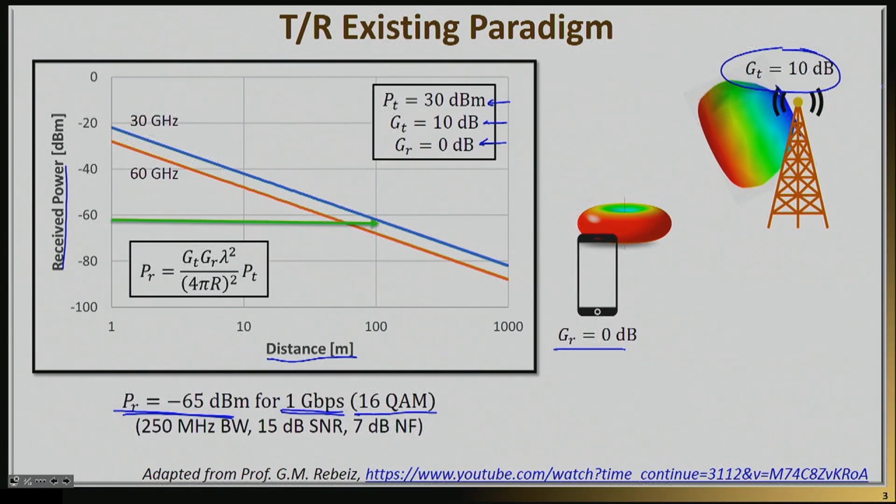So if you look into the Friis transmission equation, you will find out that, roughly speaking, if you're operating in one of these bands, 30 or 60 gigahertz, which are 2 of the millimeter wave bands that 5G will exist on, you're basically covering distances in the order of 10 to 100 meters if you must maintain a -60 dBm power range. So as you can see, the distance, once you move to millimeter wave, basically drops dramatically.